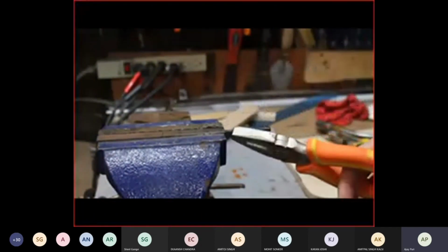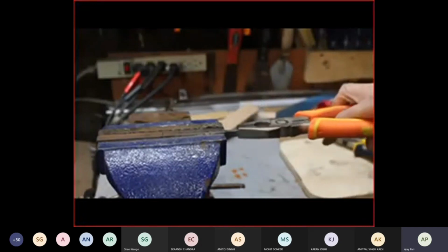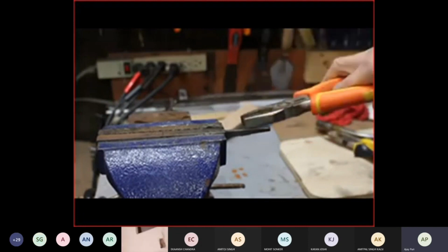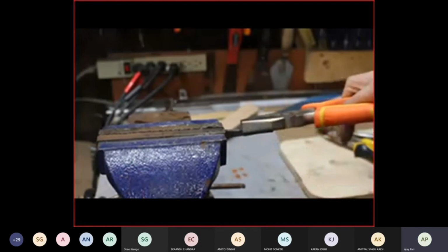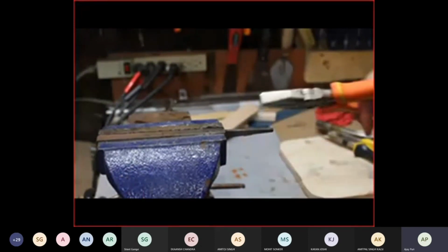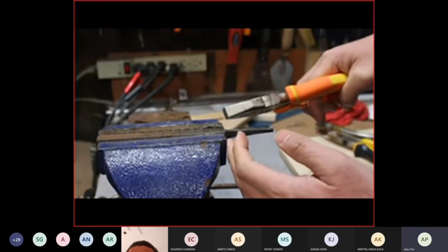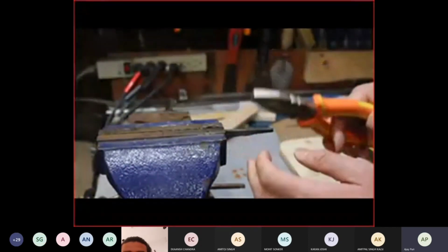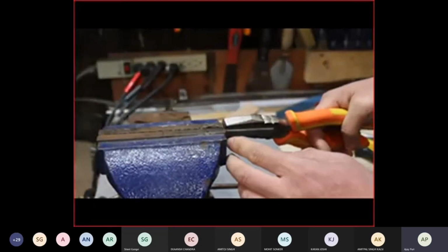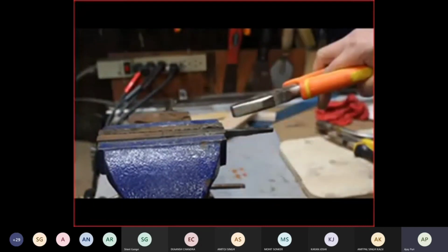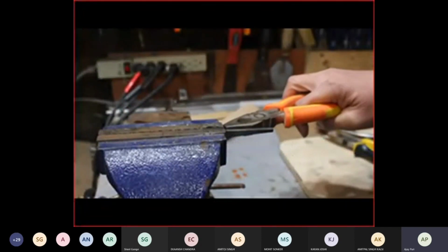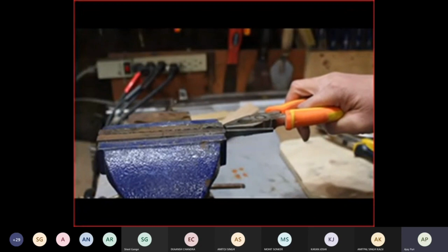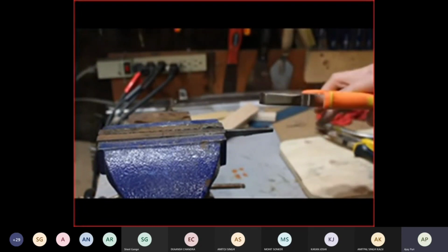And then this piece up here, where it actually kind of got tempered, has become springy now, depending on how you temper the steel after heat treating. This part up here I had originally heated and then snapped off. But because I had heated up to about here, this here didn't get up to the point where, I forget the terminology of the crystallization of the steel, it hasn't fully converted to the substance. Is it martensite? I forget exactly. Anyways, if you Wikipedia, it's in there.